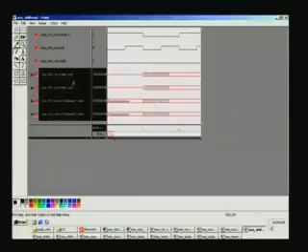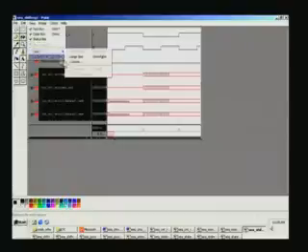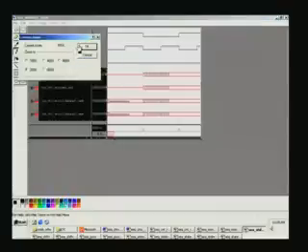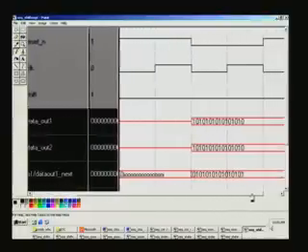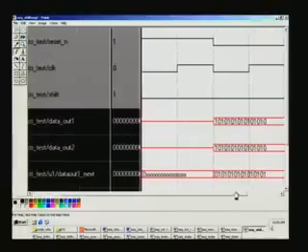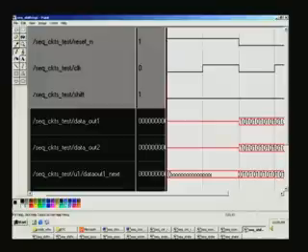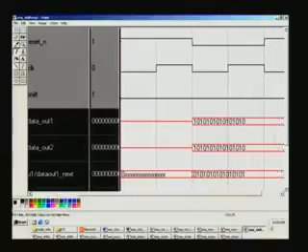So here what we do is, this is the data out 1, I think I will zoom it further. Earlier I think you had asked this question: can we have 16 bits represented? That is precisely what we have here. Whenever there is a reset active and the clock is free running, it can start any time or after the reset, and it does not really matter, because reset is asynchronous active low. Asynchronous means whenever that happens, immediately it will take effect.